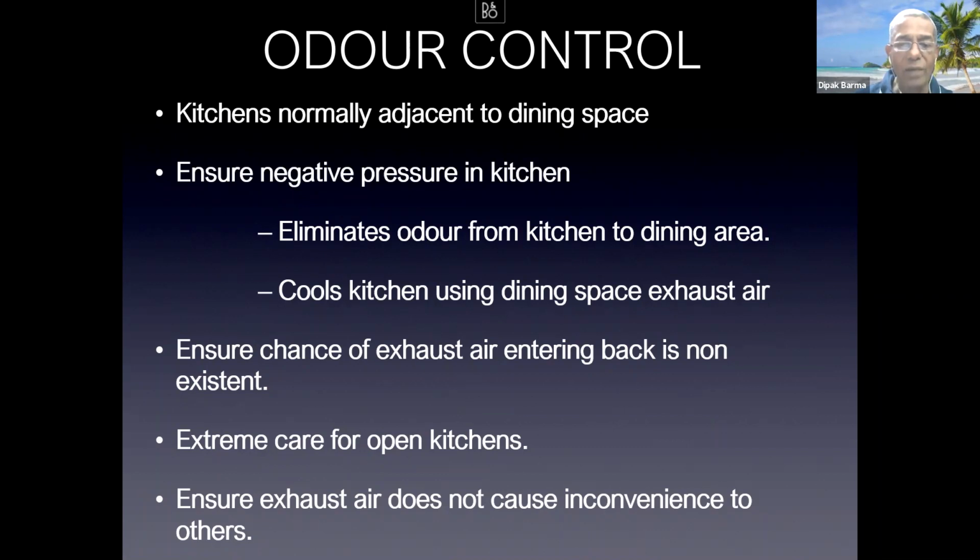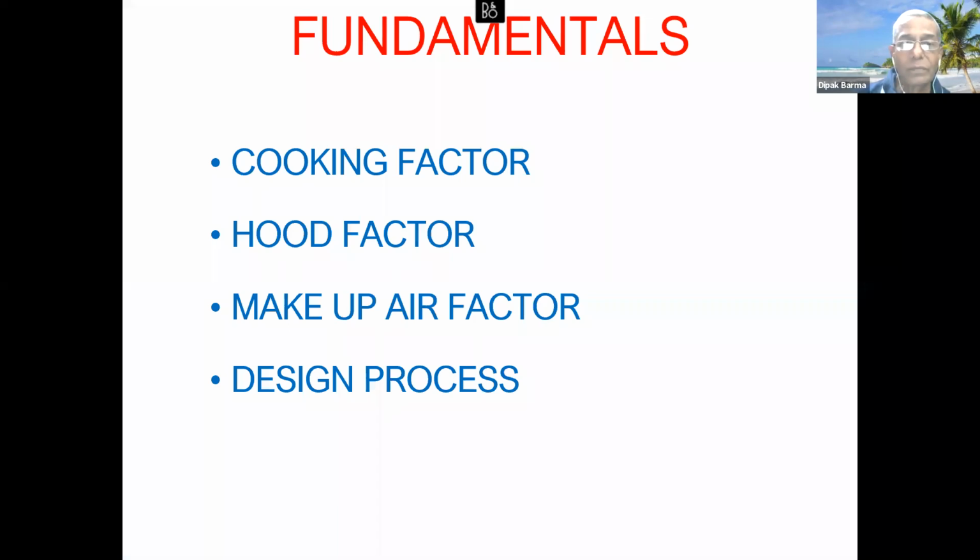Here, the requirements become slightly more stringent and higher. We have to ensure that exhaust air does not cause inconvenience to others. What we need to take into account: the cooking factor, the hood factors, makeup air factor, and the design process. These are the areas which we'll be covering now.